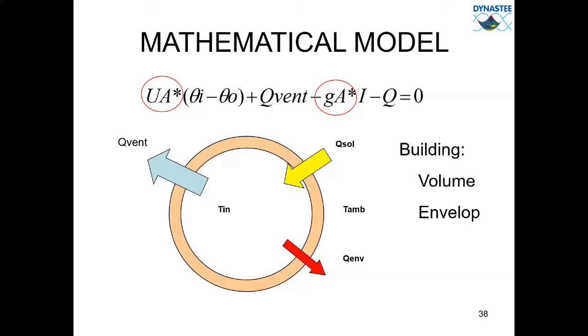We are excluding corner effects, so the whole zone is becoming a sphere where you have an indoor temperature and you are dealing with one ambient temperature. So there are no corner effects, and all the not measured phenomena are neglected. This could, however, be your starting point for the analysis.